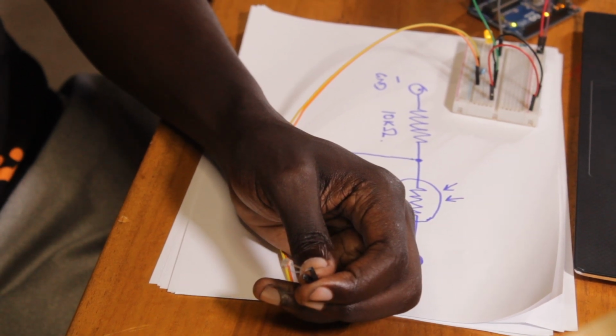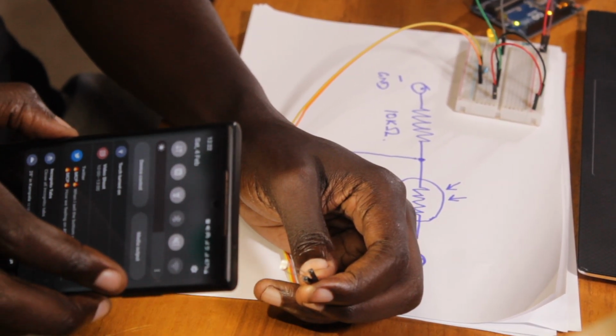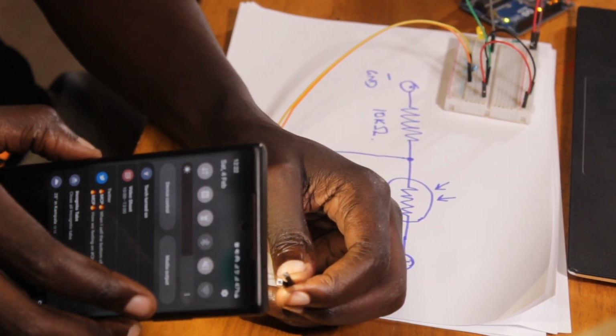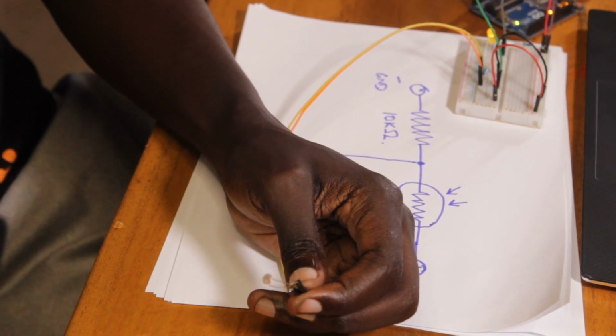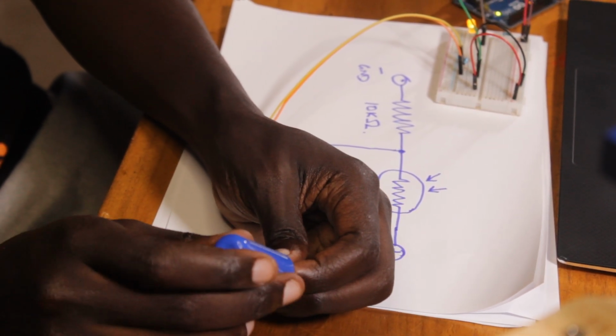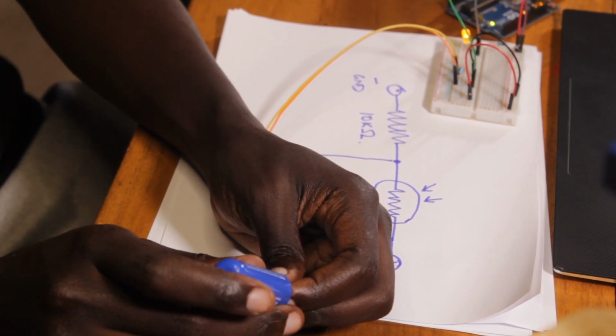So if this is your sun that's rising and then gets to daylight in the morning, you can create a value where your LED goes completely off. Or if it's full darkness, then your LED is fully bright. And that's it. Very simple. Obviously, you can tweak the circuit so that it's completely off or completely on. That's really dependent on what you're trying to do. But for now, we are basically increasing the brightness depending on the amount of light that the LDR is receiving. There are very many ways you can apply a circuit like this. It's really up to how creative you want to be.